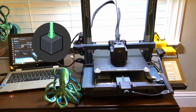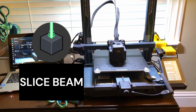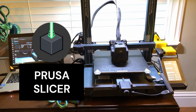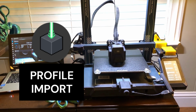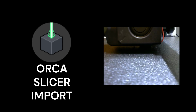So, quick recap. On an Android device, we can now slice models directly from our phone using SliceBeam. SliceBeam is a mobile slicer that is based off of Prusa Slicer, and you can use default profiles or your own, which you can import from Prusa Slicer and Orca Slicer. I am very glad that we can import from Orca Slicer. There can be some errors when importing from Orca, but this usually happens when you piggyback off of other profiles.